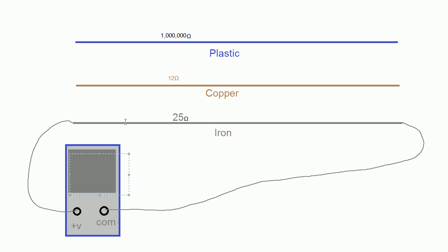And with conductors, it's incredibly low, such that it's almost unnoticeable. It can't be noticed. I'm not sure if I said that right, but you get the idea. But with insulators, it gets to be very, very high values. Say, for example, I know that the very, very rough approximate breakdown voltage of dry air is about 3 million volts per meter. So you need 3 million volts for a spark to develop across 1 meter of airspace. And that's really the only breakdown voltage number I have memorized.